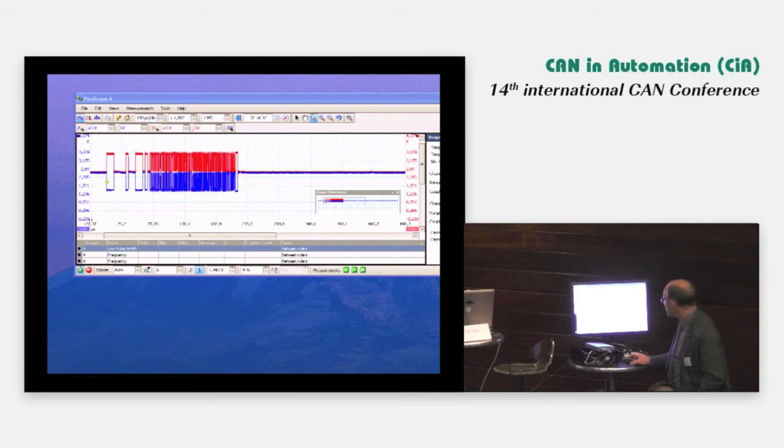With these tools, we can also check things while running. In the logic, we have put in a dynamic clock. So we can add a clock error to one controller, and then we can see at what clock error we get error frames. That's interesting when you do this, because the clock variation you can have in a CAN system is not only static.